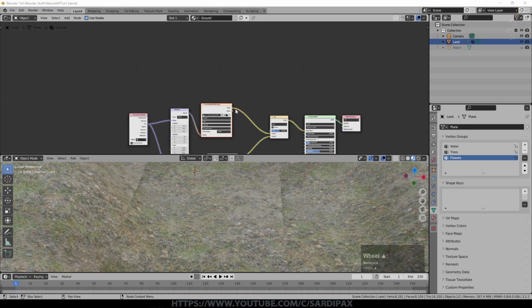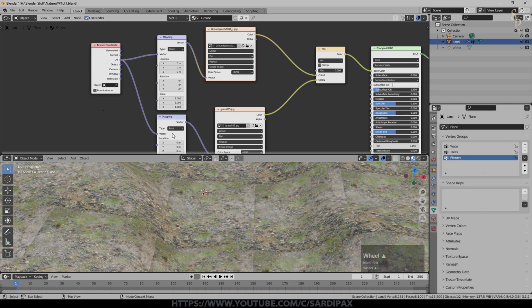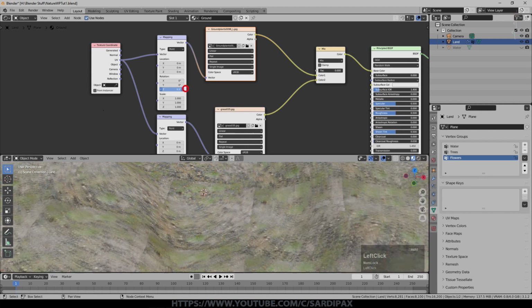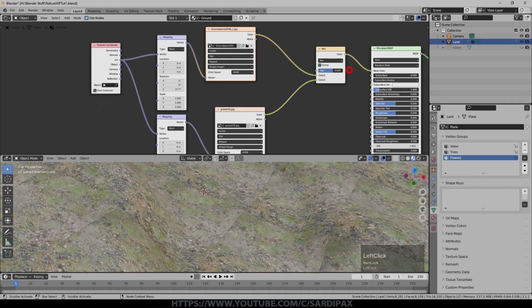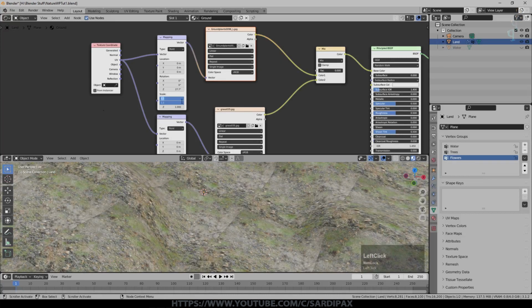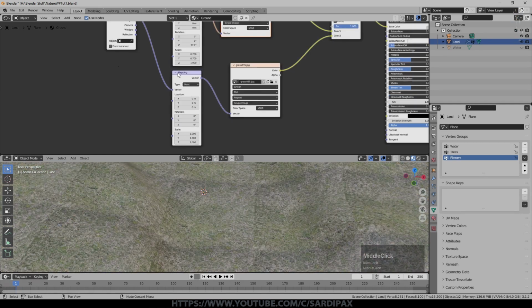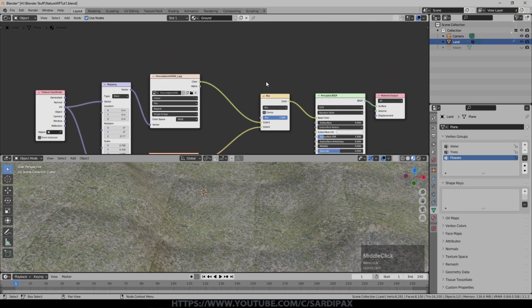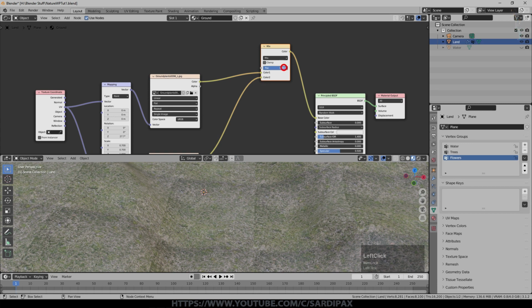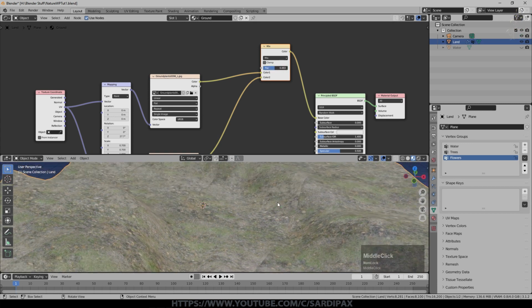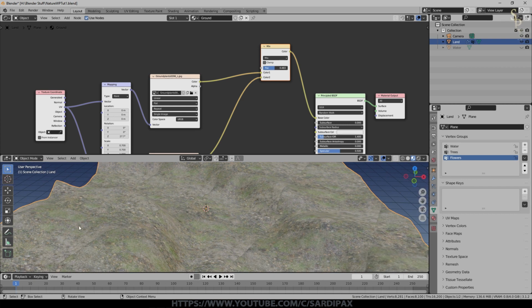So the first thing I'm going to do is rotate one of them slightly. Come over to this one, and under rotation, I'm just going to turn Z around a little bit so that it doesn't align. And now if I switch between one and the other, you can see they don't align now. I can also adjust the scale slightly. So we'll go with 0.7 perhaps for that one. So they're now both different scales and at different angles. This mapping node was just here in case I needed to independently tweak the scale. So we've got that, and now what we need to be able to do is to be automatically switching between one and the other, because even if I switch to 50%, essentially we get the worst of both cases because we can see the tiles of the diagonal one and to some extent the tiles of the other.